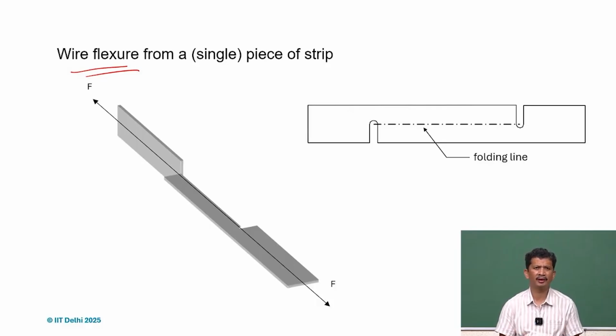In buckling, yes, the load capacity will be limited under compression. Secondly, getting very thin members and clamping those members is also very difficult. So the assembly will be challenging. So what are the other ways, if you want to get the same behavior as the wire flexure, that we can work around?